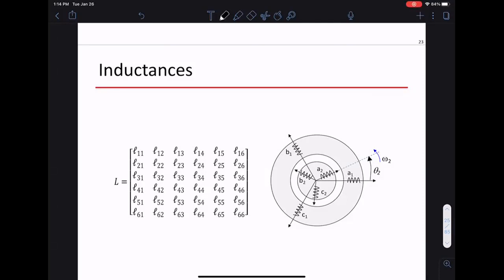Getting here is not hard, because you draw the diagram, there are 6 inductors, and you write down this matrix. This is the natural matrix right there. The crux of the matter is what you do once you get to this matrix. There are 36 numbers here, and you have to keep track of all 36 numbers. So any suggestions, any ideas of what to do here?